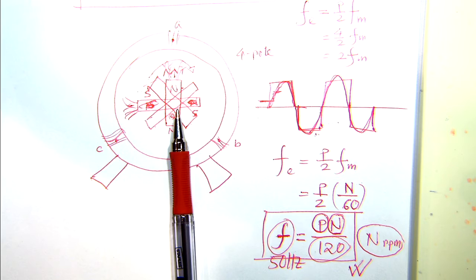If we have more poles, would the weight increase the speed? So you have to factor that in? It would just increase the rotational motion, so the torque of the prime mover would... The prime mover has to be more powerful, because you have to rotate that to get this speed anyway.